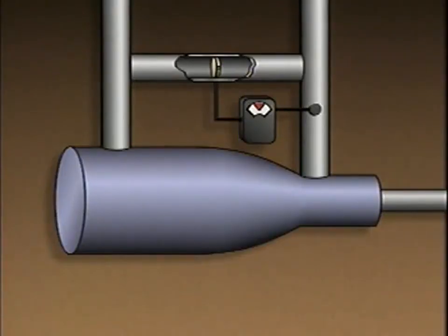One method that is used to maintain this flow rate when the demand is low is to recirculate a portion of the compressor's discharge back through the compressor. This simplified illustration represents an axial compressor with a common type of surge control system.